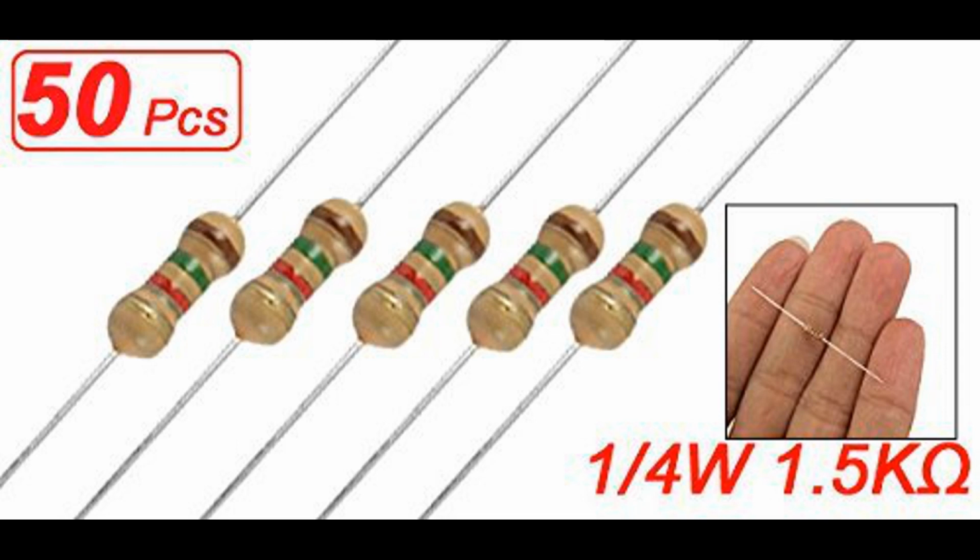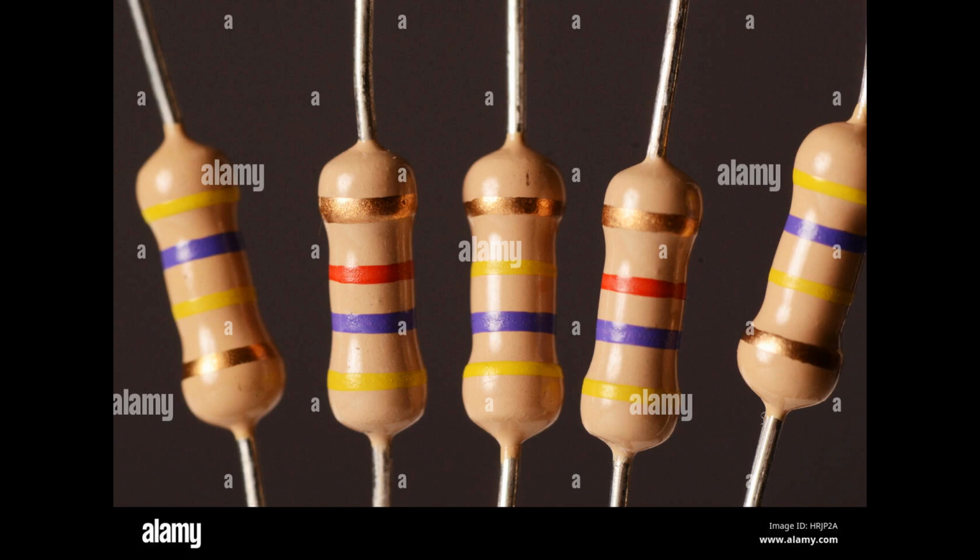Definition: the temperature coefficient, Tc, of a resistor is a numerical value that indicates how much the resistance of the resistor changes in response to changes in temperature. It measures the sensitivity of the resistor's resistance to temperature variations. Unit of measurement: the temperature coefficient is expressed in ppm/°C or ppm/°F, where ppm stands for parts per million. It quantifies the change in resistance per 1 million units of resistance for each degree Celsius or Fahrenheit change in temperature.